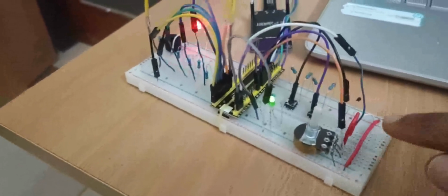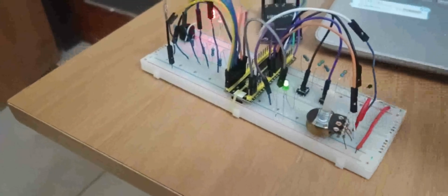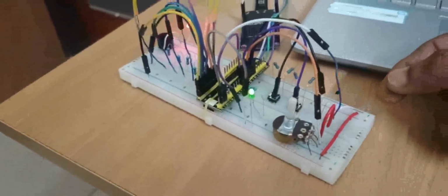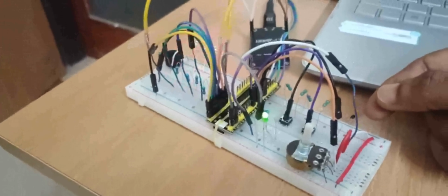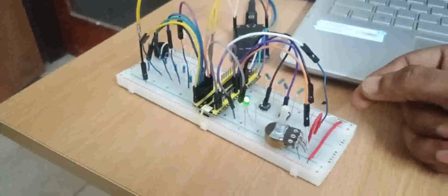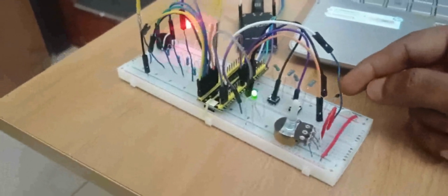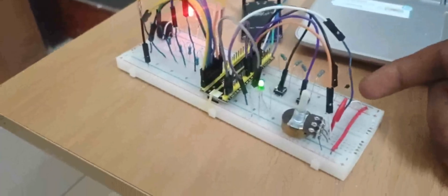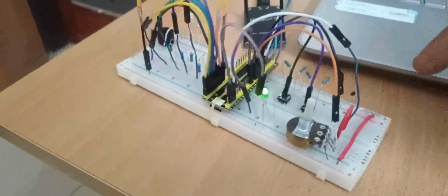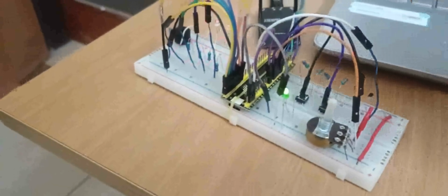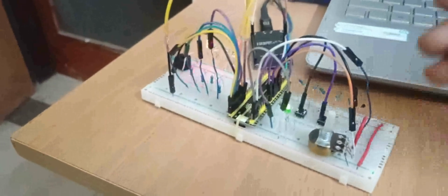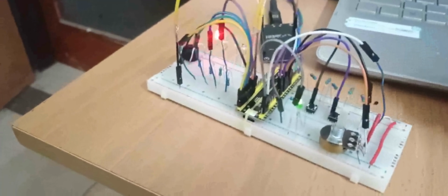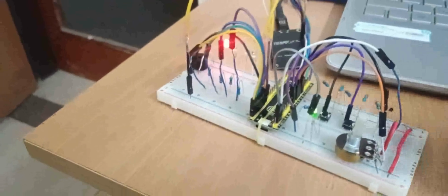That temperature is set using this potentiometer, and temperature is sensed using this NTC thermistor, that is negative temperature coefficient thermistor. If the temperature rises, then the resistance of this device falls, and that is detected by the microcontroller. If the temperature rises above some certain threshold limit, then